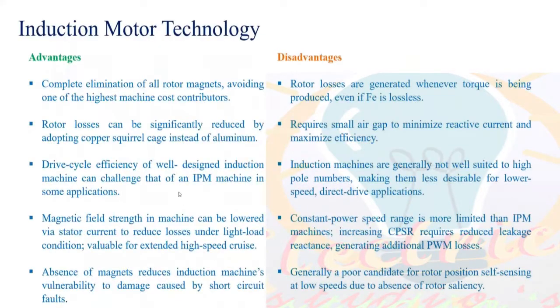And because of the absence of magnets, there is no problem. You don't need to worry about high speed operation. Because if it is a PMSM motor, I need to worry, because when my motor runs at very high speed, there are chances that the magnets can get flung out, or get damaged, or get stressed. In an induction motor, since I don't have magnets, I don't need to worry about high speed operation. So induction motors can do a fantastic job when running at high speed.